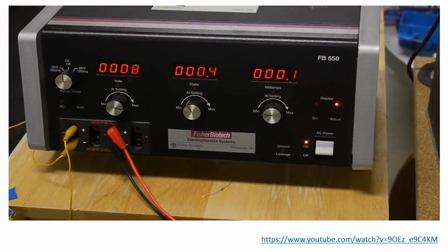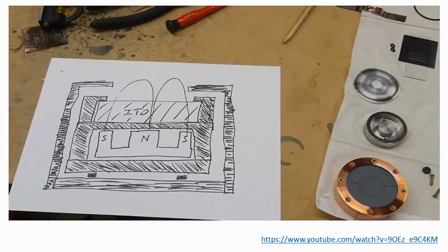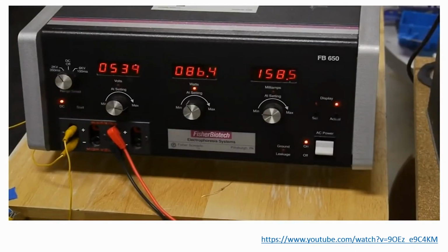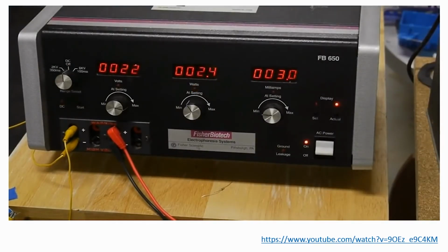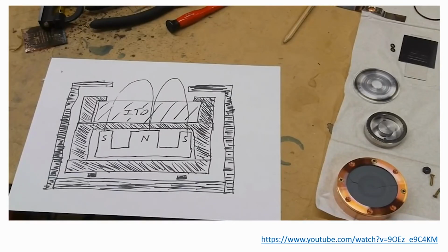Besides all the stupid safety interlocks that make it difficult to use, the supply goes into its current limit condition too quickly, and it's hard to get a consistent voltage and current out of it. It is nice that it has a constant power function, so you can set a desired wattage and then play with the chamber pressure, and it will balance the voltage and current without exceeding that power limit. However, I think for future experiments, what I'm going to use is just a microwave oven transformer with the standard diode and control it with a variac.